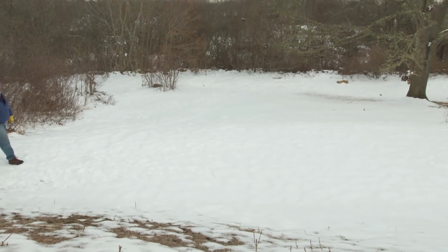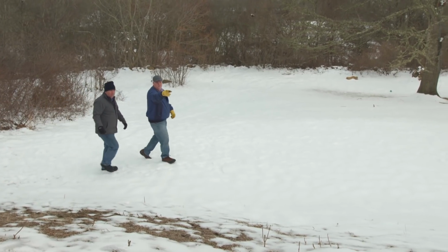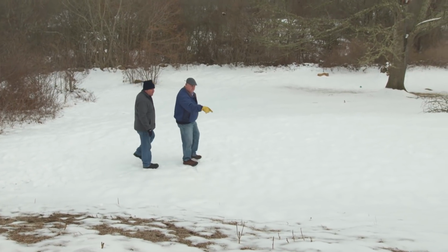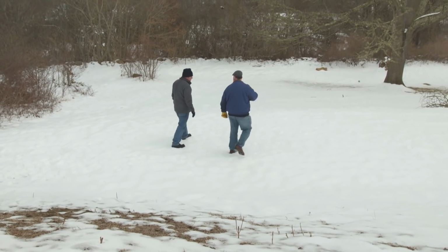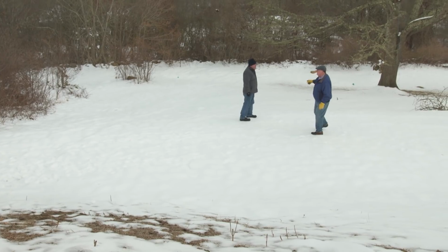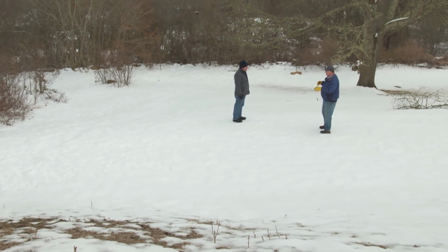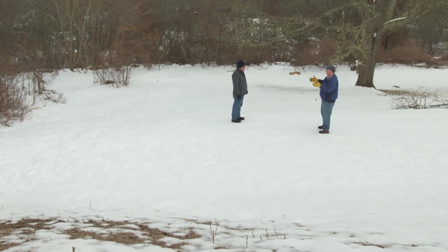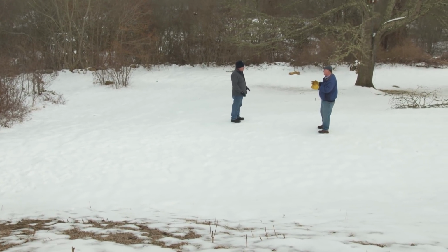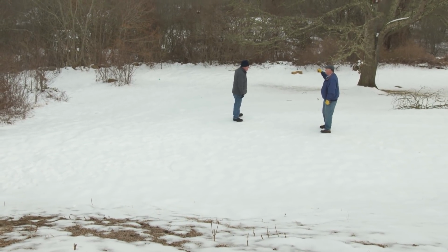All right, so our drain line leaves at the basement level right out to here, right? Correct. Well, sort of, but it comes over from this corner a little bit more. Okay. And then it comes down, it's at the basement level, comes down here to the septic tank. Septic tank's right about here? The septic tank's a little bit lower, it's down in here. It's 5 feet by 10 feet. It's got 2 24-inch covers, and it's got a large flat cover as well. It's about 3/4 of the size of a sheet of plywood. Will it stick up or? It'll be flush to grade. Okay, great. And where's the leaching field? Let's go down, I'll show you. Okay.